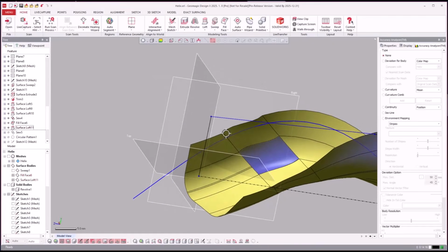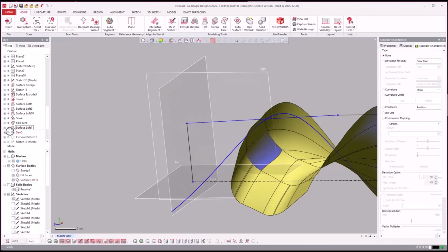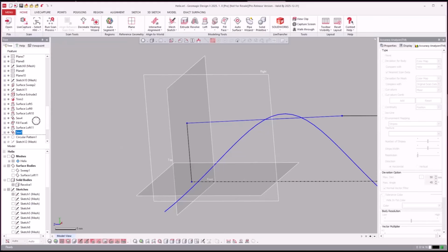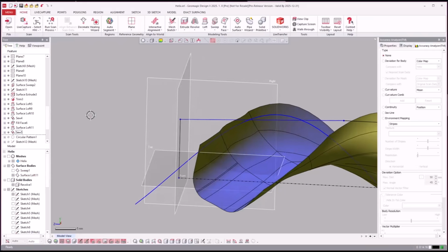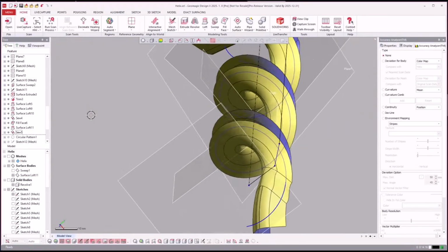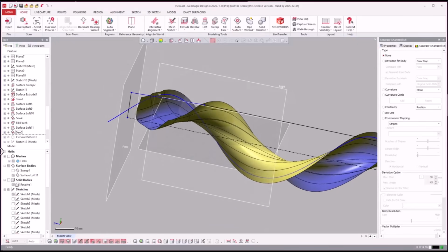You see here, sometimes this happens where it does the normals in a different direction. Sometimes it does not matter. You can just sew it together. You notice they didn't do a flip normal and then sew. It's fine. So when they sewed it together, it matched the normals to the entire surface.